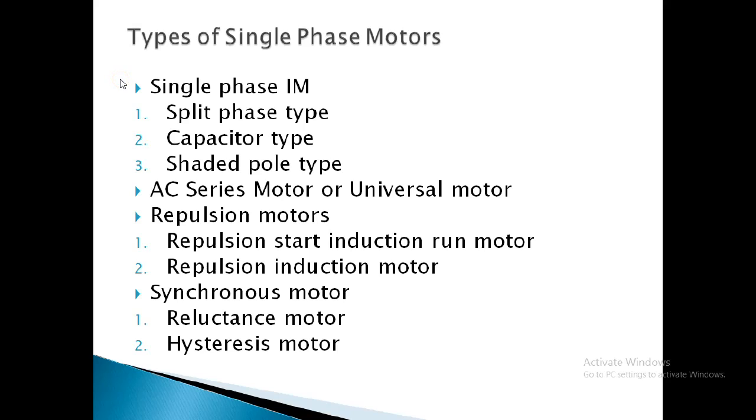Single phase induction motor is again classified into three types: first, split phase type, second, capacitor type, third, shaded pole type. Repulsion motor is classified into two types: repulsion start induction run motor and repulsion induction motor. Synchronous motor is classified into two types: reluctance motor and hysteresis motor.